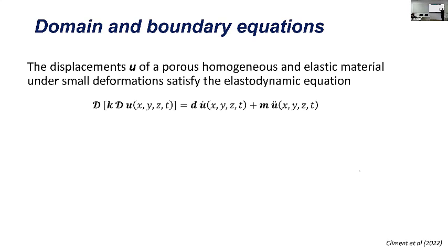And we are working using Biot's theory. So we are dealing with a biphasic medium. So these U that you see here are not only the displacements of the solid, but also the displacements of the fluid are considered. And it happens the same with the stresses. We consider the stresses of the solid and also the pore pressure. This M is the mass matrix, this D is the damping matrix, and the K is the stiffness matrix. And this is a differential operator. I think it's called the adjoint differential equilibrium operator.